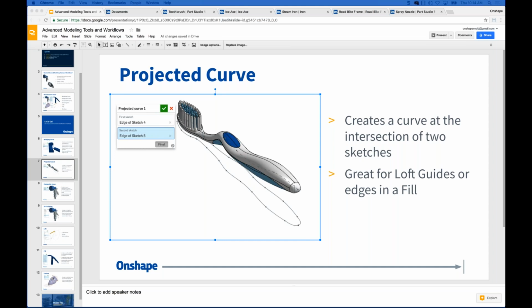I'm not sure I totally understand. It's a spline. It's not a variable radius curve. It's a spline, and it's not driven by lines that extend. Right? It's simply a spline. It's as if you were to sketch a spline and then constrain the ends of the splines tangent to the surrounding geometry. Right? You would get a very similar shape if you did that with the spline command. And by the way, the magnitude would be the amount that you extend the spline handle. Right? That would give you the equivalent of the magnitude.